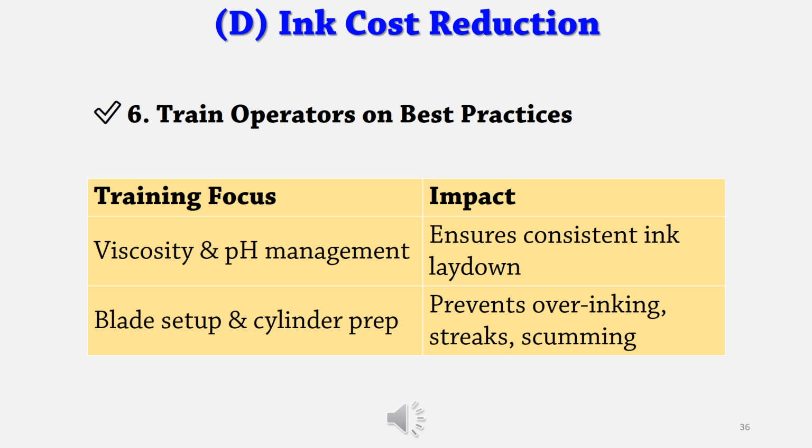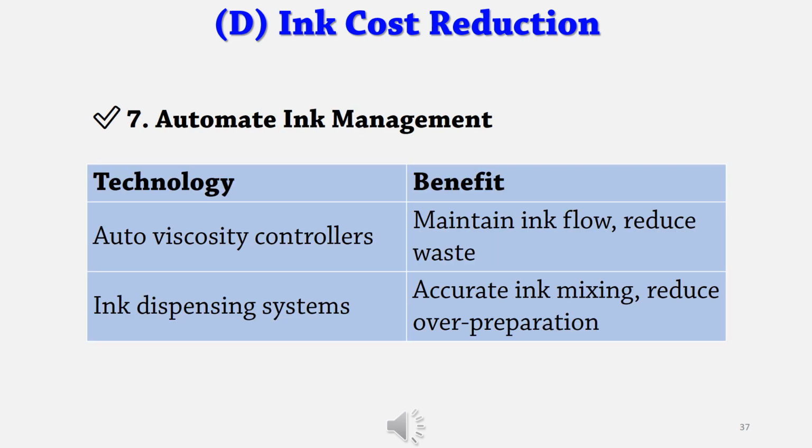Training operators on best practices can also help you to reduce ink cost. Train operators for viscosity and pH management, blade setup and cylinder preparation. Automated ink management systems like auto viscosity controllers and ink dispensing systems will help you to reduce cost.